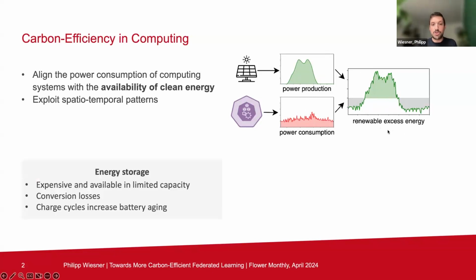The most straightforward idea would be to store it, so we transfer it through time to use it at a later point. The problem with energy storage is that it's really expensive, and it's only available in limited capacity. It doesn't make sense to buy hundreds or thousands of batteries if they're idle 90% of the year, just to accommodate some peak loads. Additionally, we have conversion losses, increased battery aging with frequent charge cycles, and so on. So energy storage makes sense, it's important, and it mitigates the problem to a certain degree, but it's not really solving the problem.